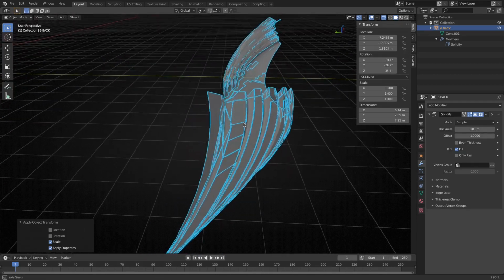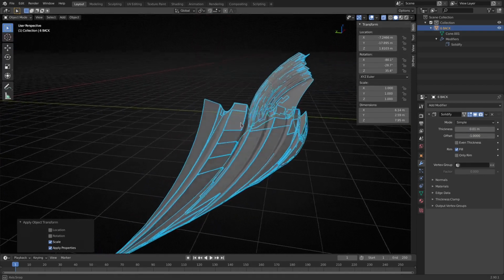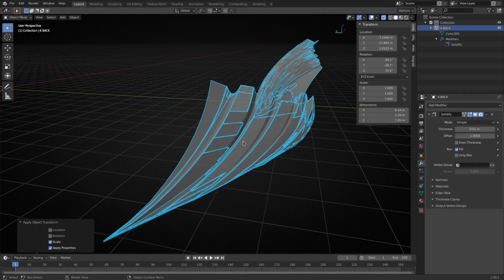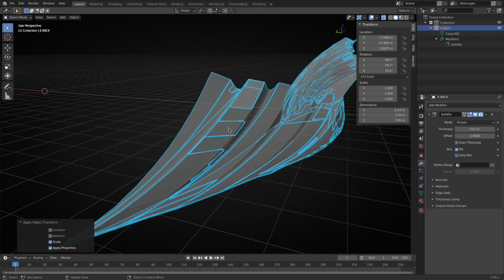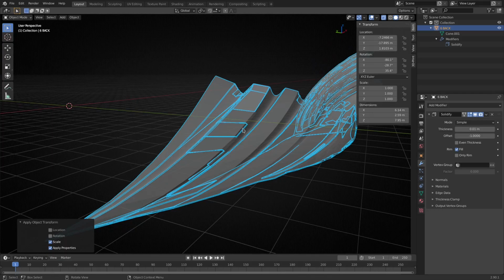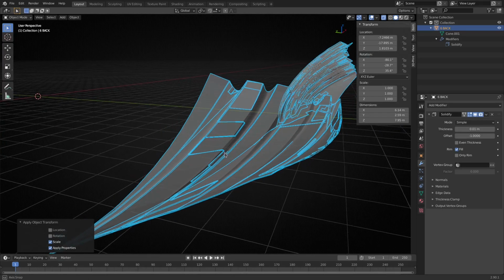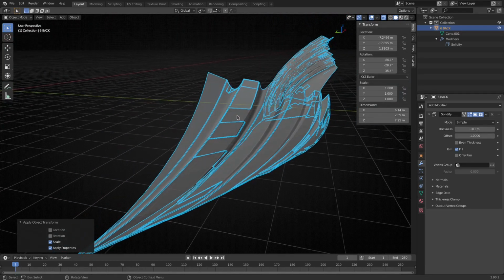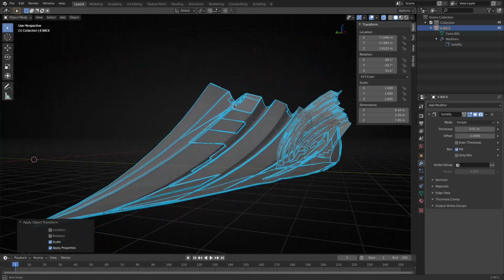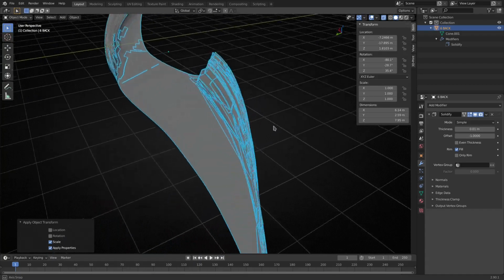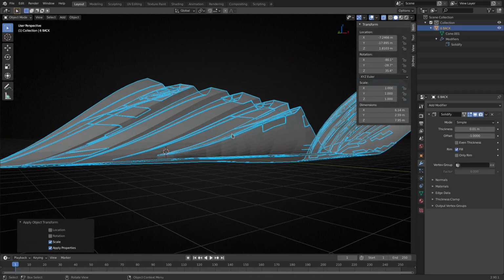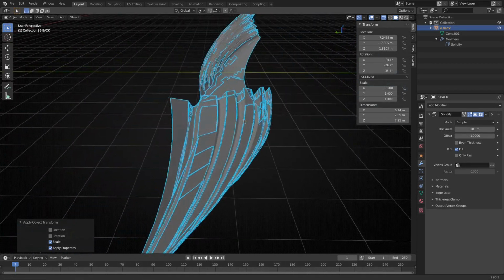Okay, so the next thing that's immediately apparent, and this file was already in X-ray view, is when you look at this model, you can see holes in it, right? You can see this wireframe, selection wireframe, sort of inside the model, you see these edges. This normally indicates that there are some sort of holes in your model. Now it might be literal holes like missing geometry, or might be something else, and this is just a good indicator that something is wrong with the geometry. As you can see, it's all over the place, on that part, everywhere basically.